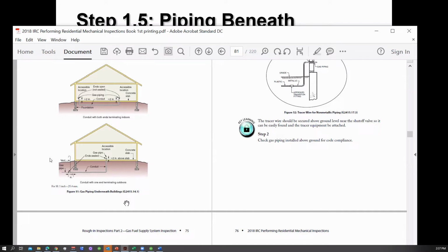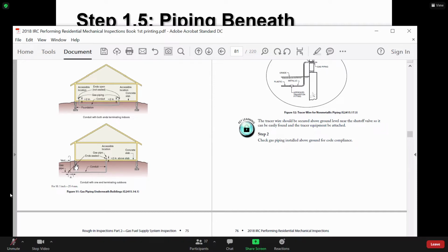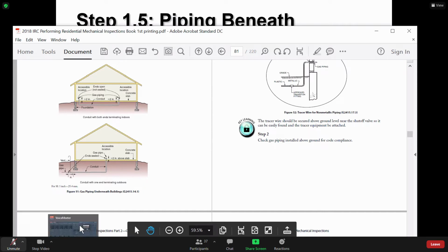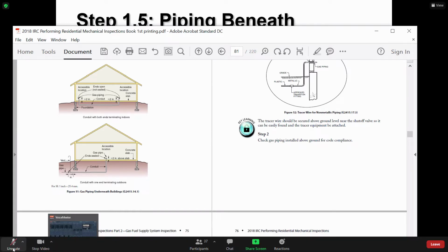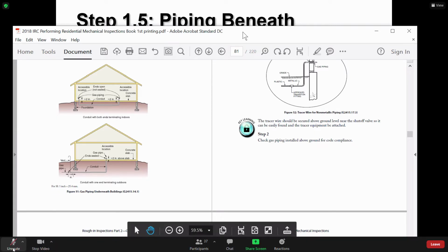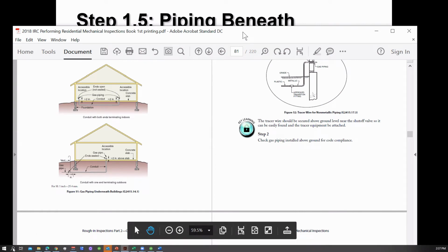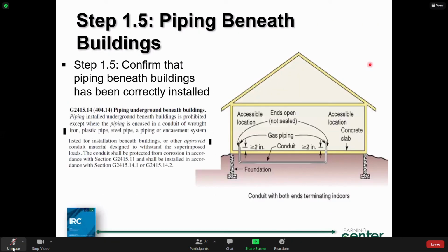But I must point out as well, you need to make sure if you're going to do this, look at where this is in this orientation here. If I take a look at the building's foundation, it's right in the bearing plane, isn't it? I'm going to probably want to make sure that I don't crush the pipe or the casing around there, and probably want to take a good look at that. Maybe we'd take it through the foundation wall, what we do.